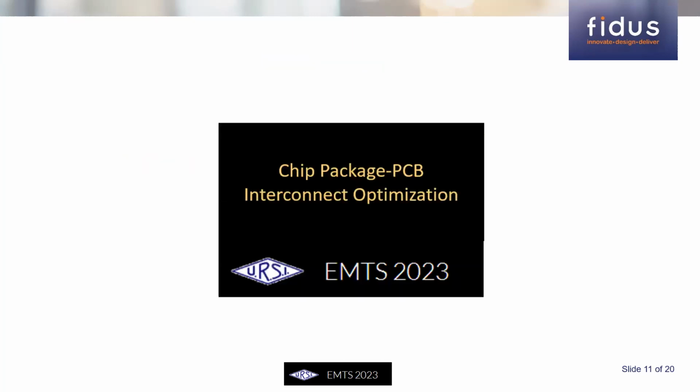So with these two things, let me start my presentation on chip package interconnect optimization. The prelude was mostly to lead to exactly what is being done here to optimize a chip package interconnect. Now, again, like I mentioned, I'm talking about really, really high frequencies. Nyquist are in the range of 50 gigahertz plus. That's where these approximations that we generally take for granted become questionable.